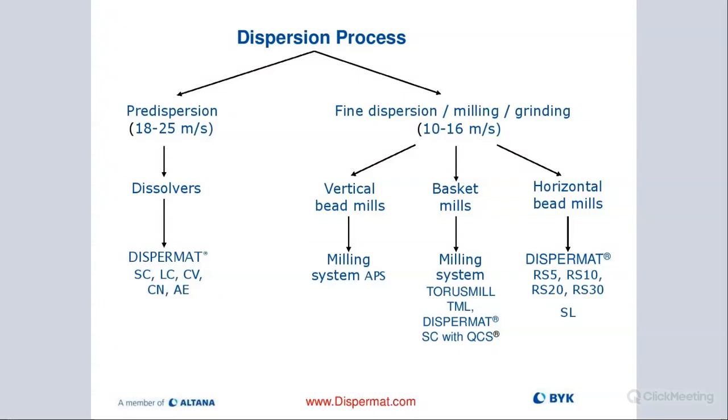Lab to bulk upscaling. How do you better correlate lab and production mixing times? So again, there are a couple of things we look at. First of all, you want obviously the diameter blade to vessel ratio, and fill rate. You want to absolutely look at tip speed, more important than anything else, like RPM, because you're going to run much faster in the lab than you ever will in production. So RPMs really don't mean much.